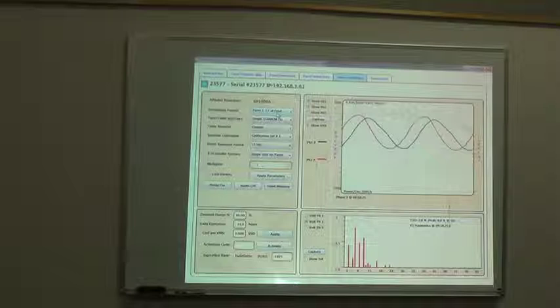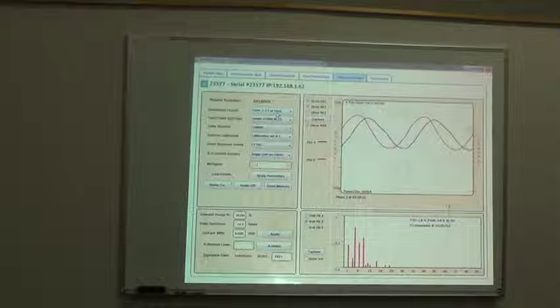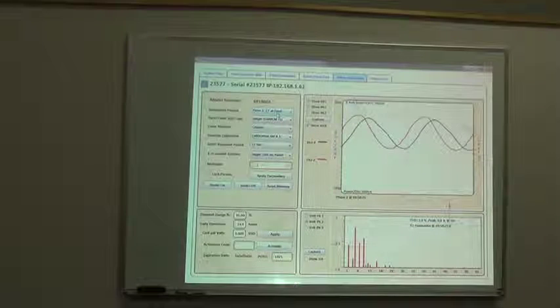They literally have panels that go far away and there's just not enough machines to put at each one, and they want to put all the machines next to the MDP, but they want to correct for each one of them individually. Then basically you put all the CTs on the load side of the system. The supermarket that we did with 10 units was all like that. We couldn't even do it any other form.